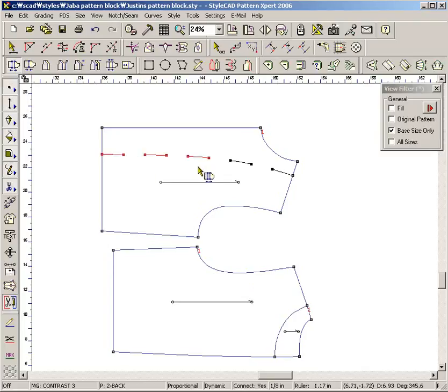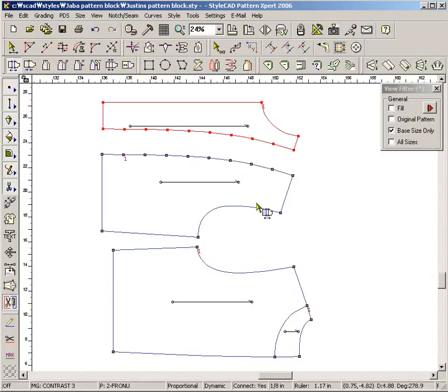If the cutting line is disconnected, select them all with the Shift key down. Left-click one of the selected lines to cut. Drag the mouse while holding the Control key to move the cut pieces. Let us show you how to join the cut pieces back into one.